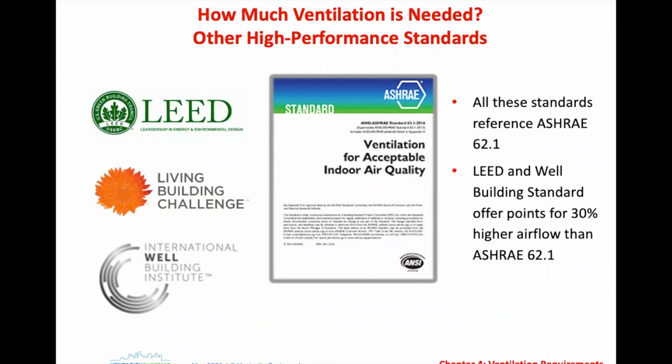Demand control and other options that you can use to optimize and make it very effective can be just as important as just adding extra air. So that's just something to keep in mind. And we find that if you're tracking CO2 levels and using demand control in a commercial application, you're able to manage it very effectively that way, and you aren't unnecessarily over-ventilating. But there are points for that, and you have to design that in. And from the design standpoint, at the beginning, determine if you're going to allow for 30% additional airflows.